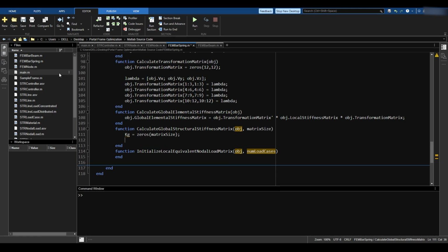What is my objective here? Let me explain this to you. The stiffness matrix can be split into 4 blocks. I've done this in the Finite Element Method explanation series, but I'll do it here very quickly. Every single stiffness matrix, at least for bars, can be subdivided into 4 blocks. Node 1 with node 1, so node 1 with itself.